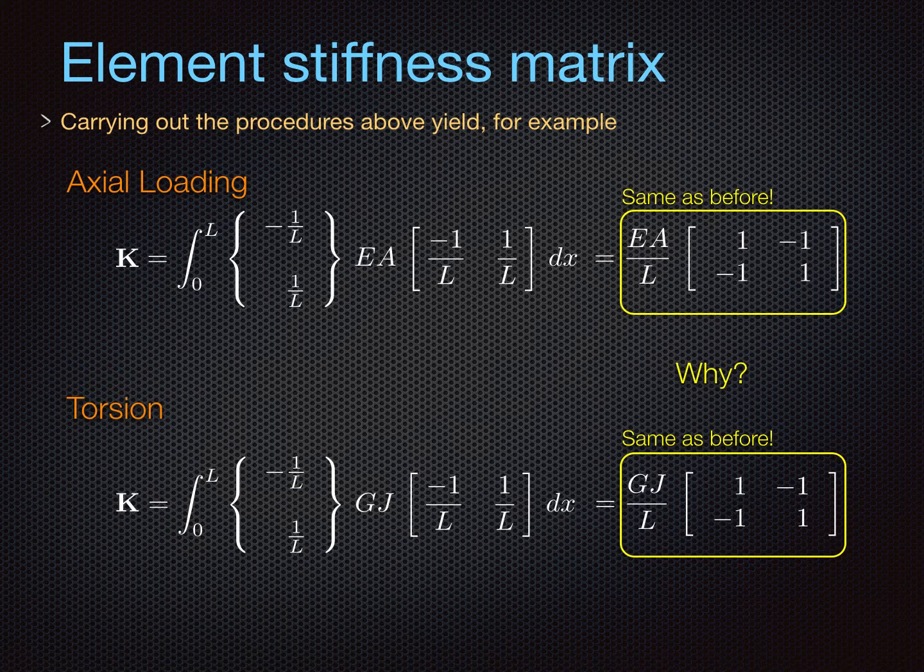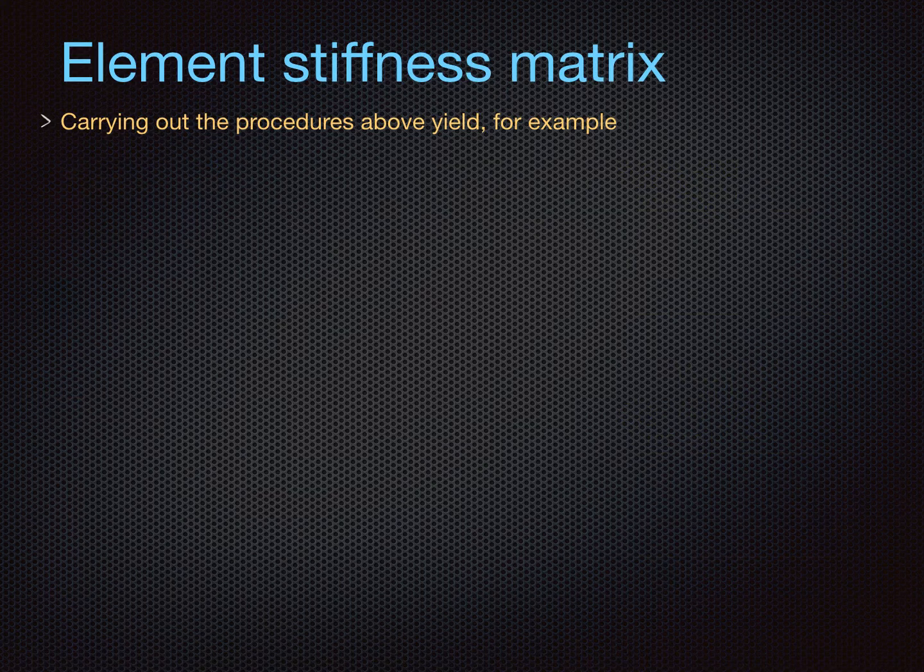If the truss or the shaft is not loaded at its two ends, or as you saw before in the example, the cross-section is not prismatic, then these matrices can still be used to obtain a principle of virtual work based solution to the problem at hand, but that solution will only be approximate, not exact.